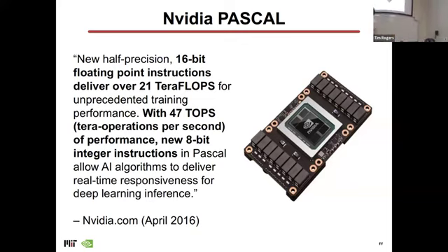This was in 2016 when they were like, oh, everything used to be floating point 32. And so they went to floating point 16. This was pre-tensor cores, okay? So they had specialized MAC units in the Pascal card that natively supported FP16 instead of FP32. And then the next generation was the Volta, where they had the tensor cores, where they only supported FP16.